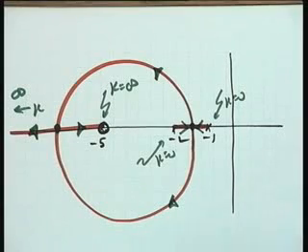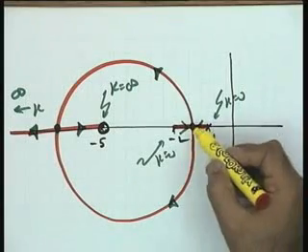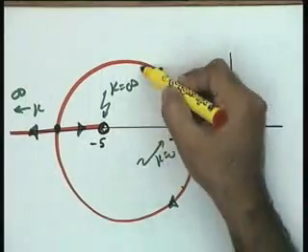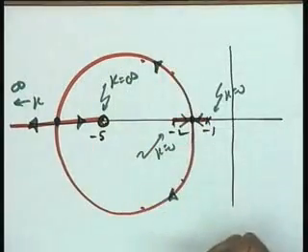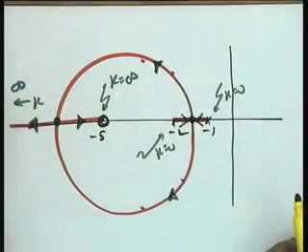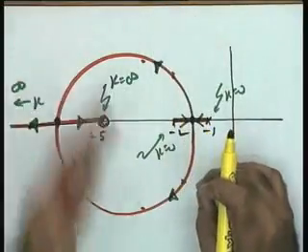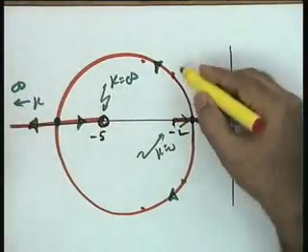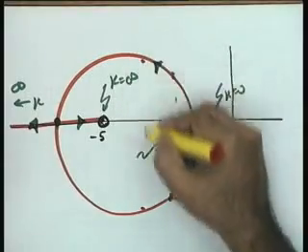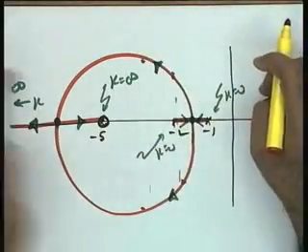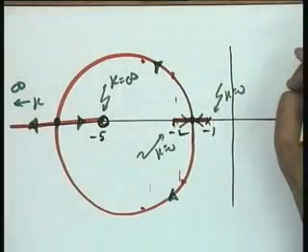And the second observation is this, that after this value of k, the roots are complex conjugate and the real part of the roots is increasing. The imaginary part, from this point to this point, is not appreciably increasing, but the real part is increasing drastically.